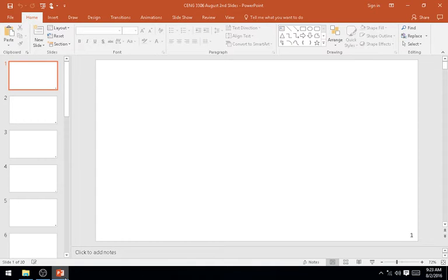So, let's see. We have two lessons we're going to get through today, but first I'm going to work on lesson 27 for the course, and this is the second lecture in elastic bending. We're going to be going over section 6.4 in the Hibbler text, and our learning objectives here are twofold. One, we wish to use the elastic section modulus, which we designate by variable S, and beam tables to design the lightest beams, and then explain the standard notation for beams in the steel tables.